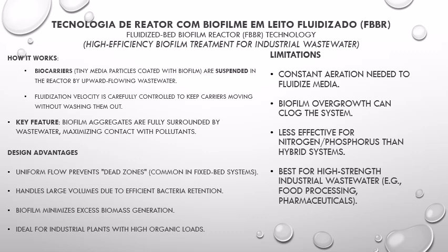The key feature is that biofilm aggregates are fully surrounded by wastewater, maximizing contact with pollutants. Also, it allows uniform flow, preventing dead zones, like we have in some fixed bed systems. It can handle large volumes of water due to efficient bacterial retention. It minimizes excess biomass generation also, and it's ideal for industrial plants with high organic loads.